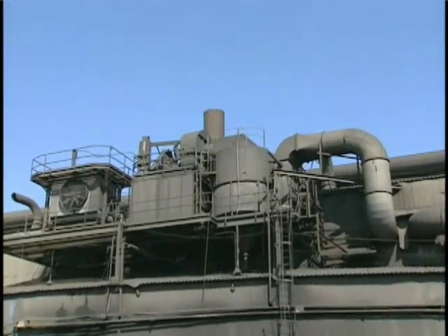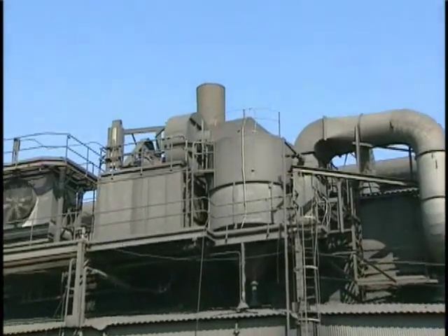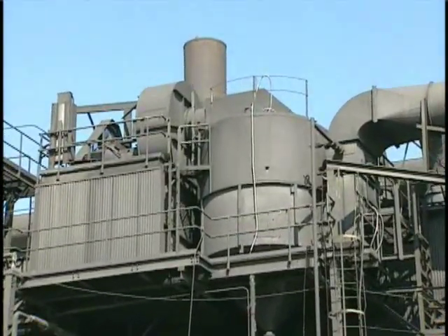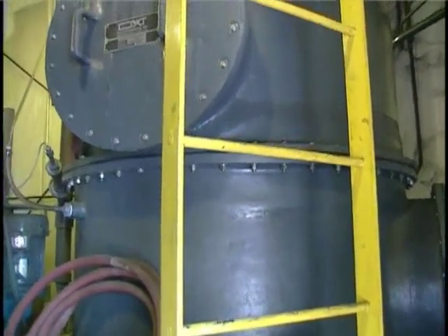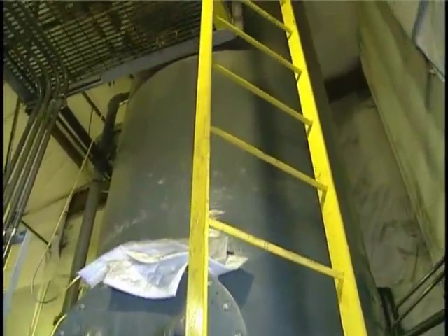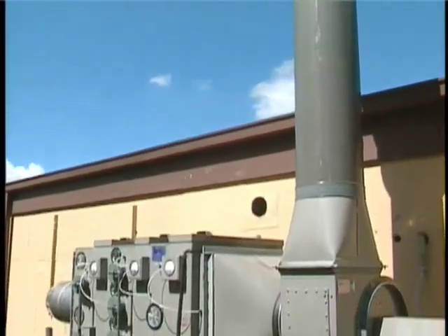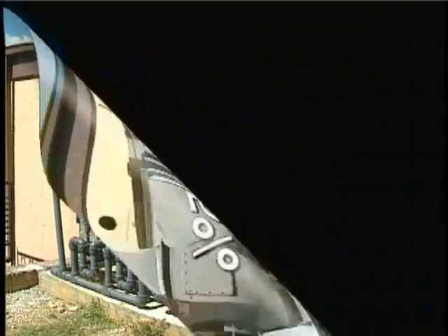In wet scrubbing processes, liquid or solid particles are removed from a gas stream by transferring them to a liquid. That liquid is usually water. However, if gaseous pollutants are also being removed, it may be an aqueous solution that contains chemicals selected to react with the absorbed contaminants. Most wet scrubbing systems operate with particulate collection efficiencies over 95%.